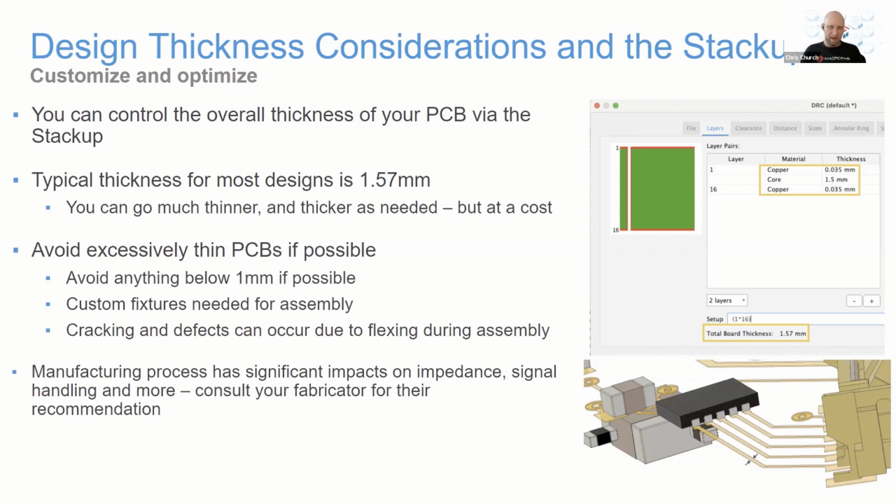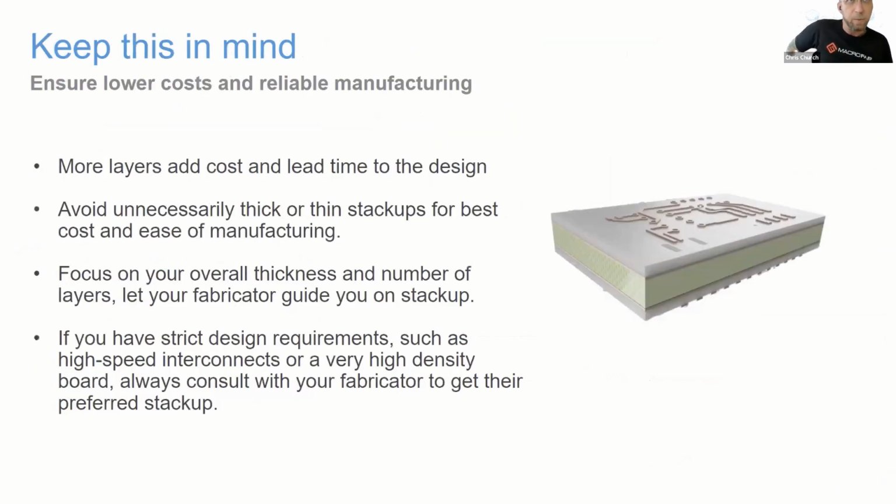Anytime you have a really high performance board, reach out to your fabricator as early as possible in the design process and get their input on your stack up and any material choices you're going to make. So again, just to reiterate a couple points we talked about on the PCB itself. It's great to have additional layers. You can route more signals, and it enables you to make a denser board. Those are going to add cost and lead time. So if you are cost sensitive, think about reducing the number of layers, especially if you're lead time sensitive.